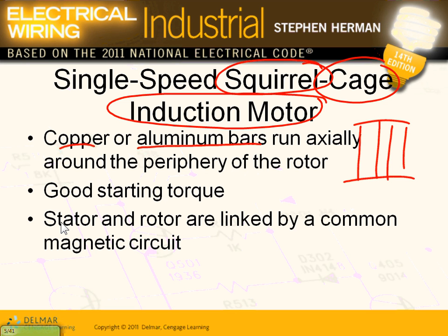Shorted at the end. The good thing, I don't want to make it a motor class, guys, because there's a lot about motors. The single most important thing when we talk to the mechanical engineers about motors is the starting torque and the running torque of a motor. Electrically speaking, we care about amps, but the mechanical guys base everything they do on the torque. How much torque you can get out of this motor is a big deal. It gives you the ability to mechanically, physically do work.